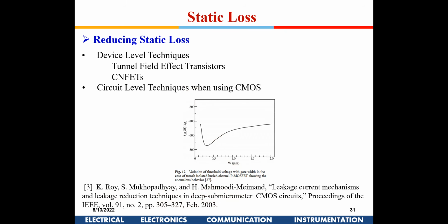if you keep width low, more resistance, lesser current, right? Okay, but that doesn't happen in a short channel. That is true for a long channel. Even for 180 nanometer, if you reduce the width, you will find a little bit of current is reducing. But when I am talking about 45 nanometer and 25 nanometer, if I reduce the width, it affects my VT. Okay, so please have a look at this paper.